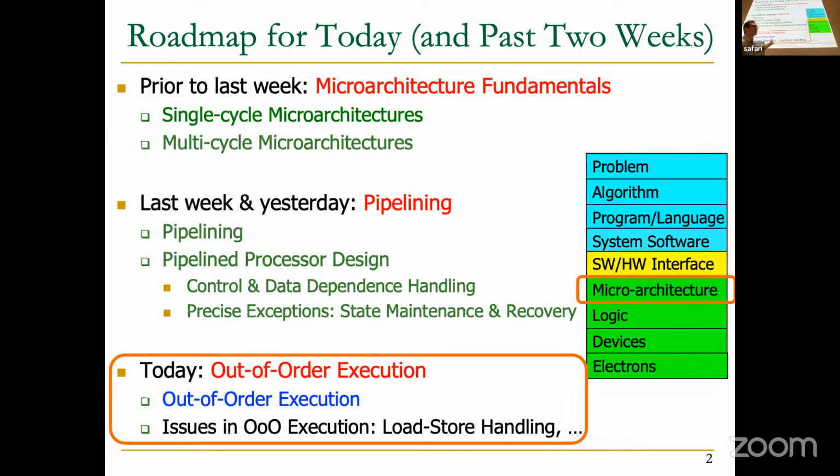Unfortunately, we don't have time to really cover load store handling, but for your own benefit, you can watch that. That's really the most sophisticated part of the machine today, how to handle loads and stores. It uses a lot of content addressable memory. You got introduced to content addressable memories yesterday. Unfortunately, that part is very difficult to eliminate content addressable memories from.